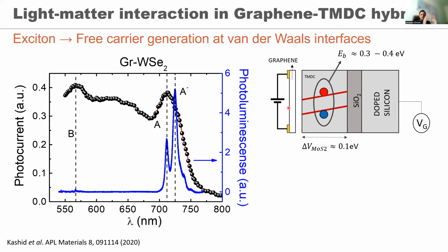However, if I did the opposite, that means graphene on the bottom and the chalcogenide layer on the top, then you will not be able to create this electric field across the chalcogenide layer. So even if you create the electron hole pair in the chalcogenide layer by shining light, the electron hole pairs will preferentially recombine within the chalcogenide layer before they can actually get transferred into the graphene. So the sequence is important in most cases. Thanks.